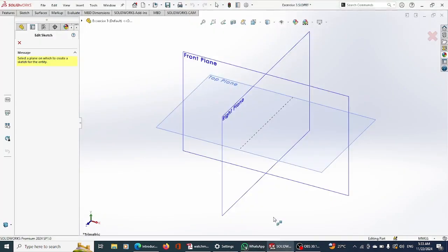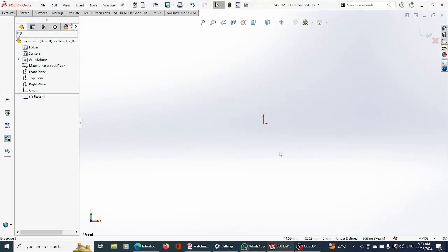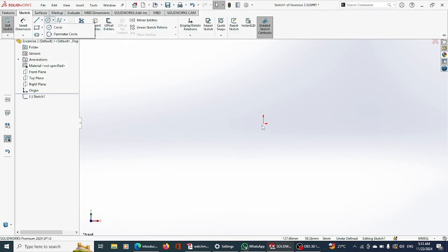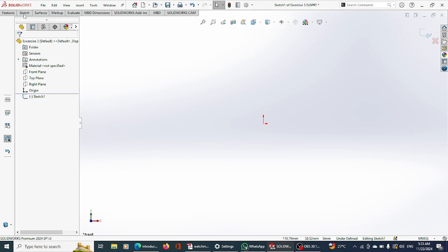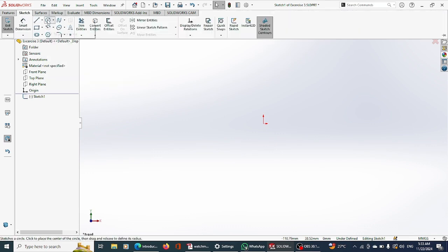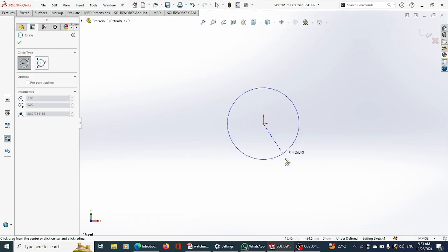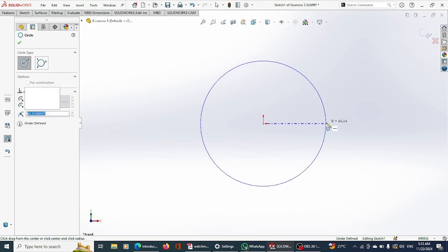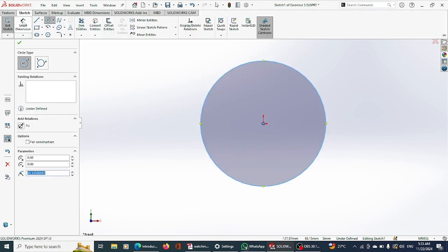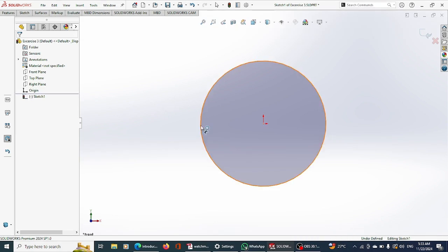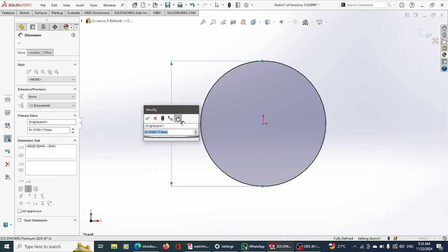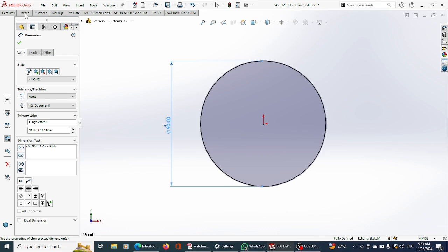So if I go here and choose front plane, I go to sketch and choose the circle tool, and then I come here. I'm moving fast because I already have the dimensions, hope you know. So if you don't get anything, always rewind this video, go and check your exercise. I choose circle, I draw the first circle, I go to sketch, I choose smart dimension, I go to this guy. Okay, we said it's 90. I press enter. I go and pick circle again.